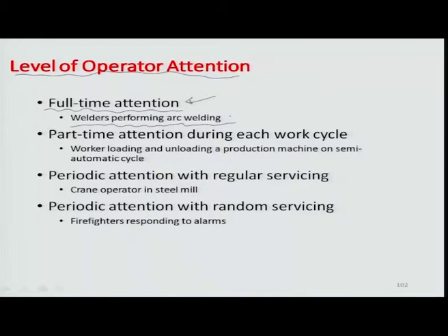On one side there is molten flow of material where the electrode size reduces, and the gap needs to be continuously maintained by the worker by moving the melting electrode nearer and nearer to the workpiece, so that you can ensure that the arc sustains itself. These kinds of operations involve almost full time attention for the concerned person working on the system.